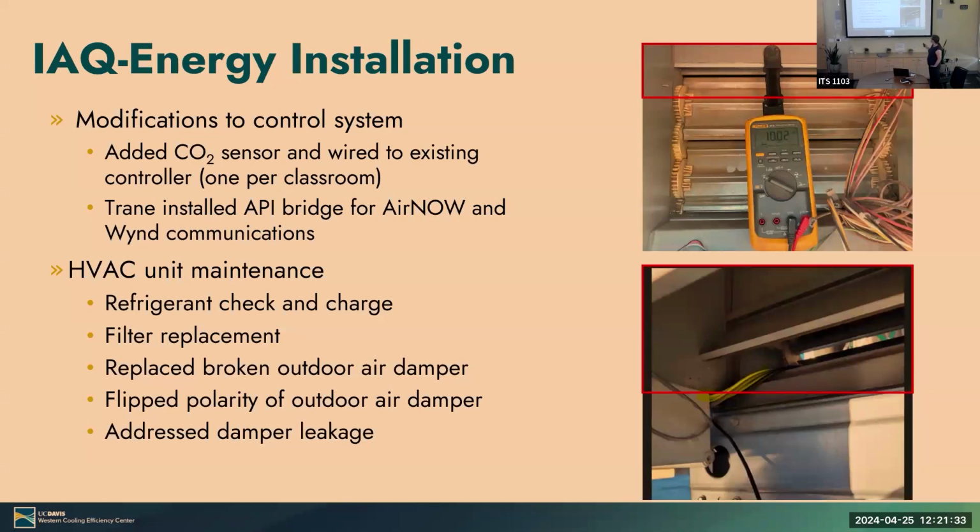This is a picture of the outside air damper. This is the outside air intake. There's also a return, and they're all on one gear system. So one actuator modulates and balances the outside air: the outside air opens and the return air closes. And then there's just a pressure relief exhaust flap. So there are 2 dampers, they move together, 2 linked dampers. Got it.